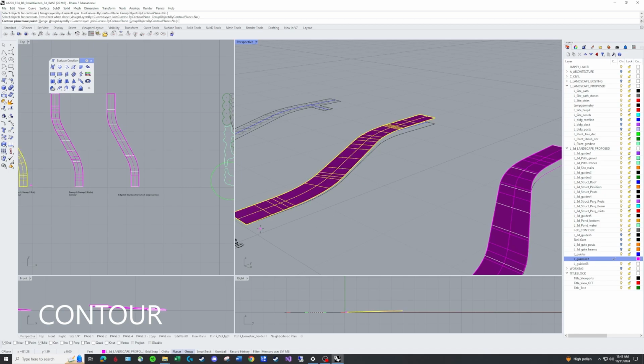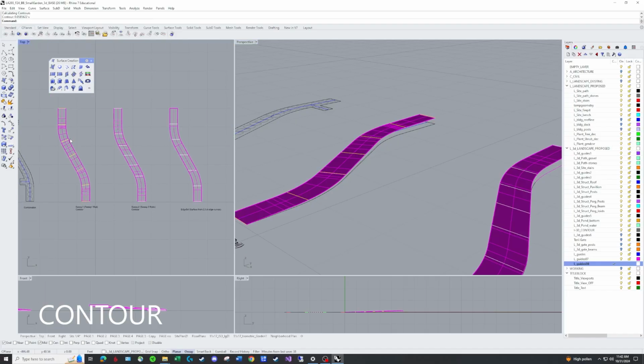Select what I want to run contours on, go back to my 0, 0, go vertical here, change my layer real quick, and contours 0.25, we'll do that, and enter. Now, what you see here is, remember, because we rotated it off this kind of strange axis, it ends up not being perpendicular to the edges.